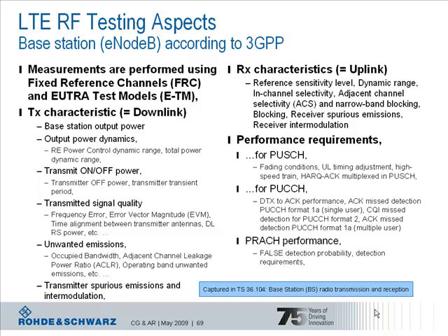Conformance testing of an LTE-capable base station is captured in 3GPP technical specification 36.141, based on technical specification 36.104, where base station radio transmission and reception is described. Transmitter and receiver tests are defined as well as performance tests. These tests are performed using well-defined fixed reference channels, FRC, and so-called UTRA test models. Fixed reference channels are used testing the receiver of the base station.